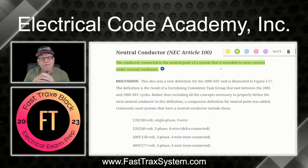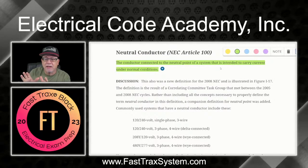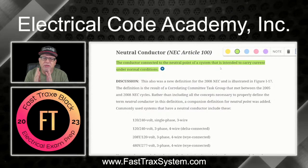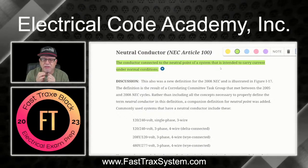So it's vital that we understand the importance of not making improper neutral-to-ground connections downstream. We cover that in our grounding and bonding series, but it's so important that you understand those concepts as an electrician, especially when I look at social media and see it done wrong so many times. That's a serious safety concern.